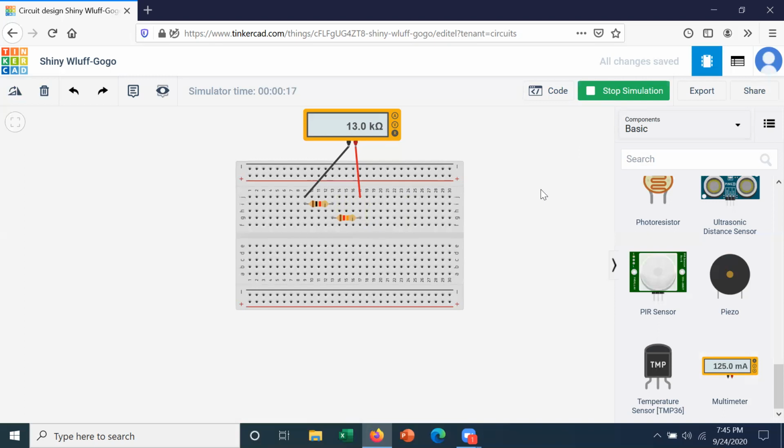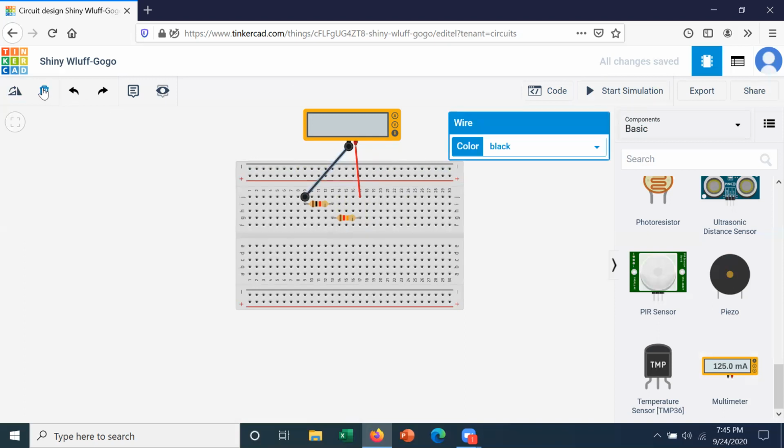As long as I'm doing this, let's stop the simulation, and let's click this guy here and throw it in the trash can. So I get rid of that lead. Let's grab a battery. Well, let me do another thing. I'm going to take this guy here. Let's make that a 9K ohm resistor. And it's weird now. It's white, black, red. 9K ohms. And I'll go down and get a battery.